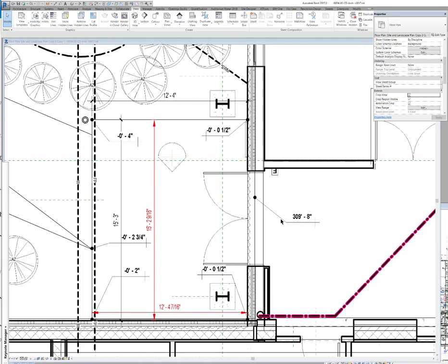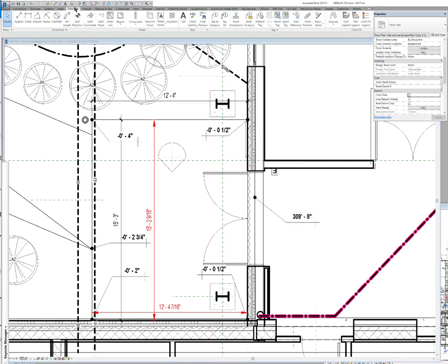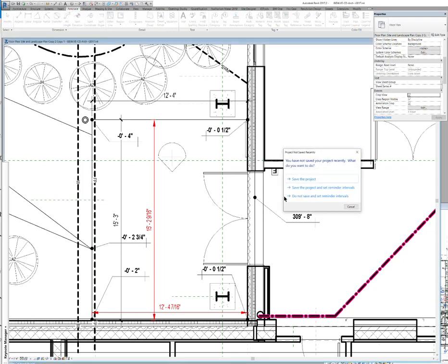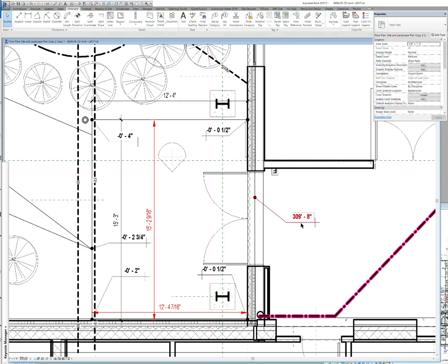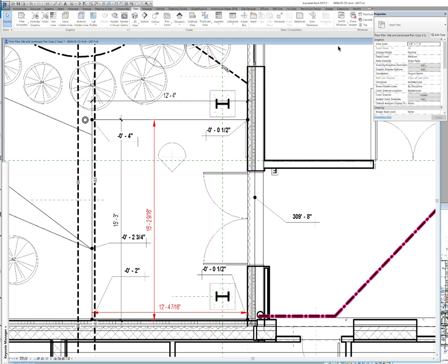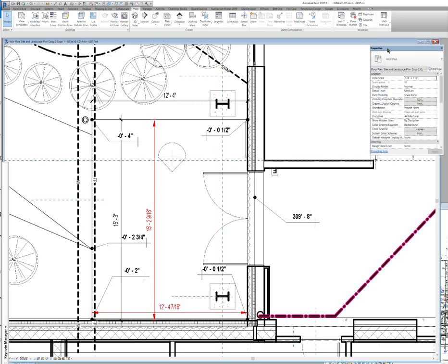So the first floor elevation, and of course you probably know that there is an elevation tag. So you can find that. It's under annotate, spot elevation, and you can modify them and make different types of ones. This is the one that I'm using. I created it. And I've gone into the view and made a shortcut, which is EL. Going into view, it's hid behind here, I think. User interface, keyboard shortcuts, and I've just called it EL so that you can tag things real quick.